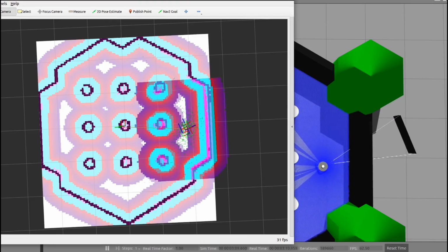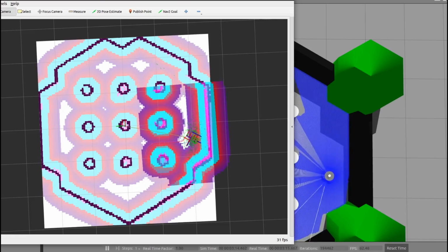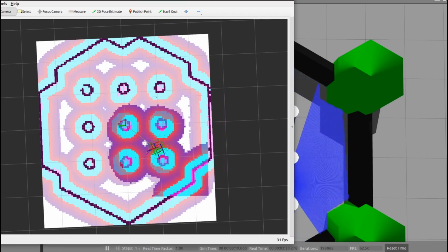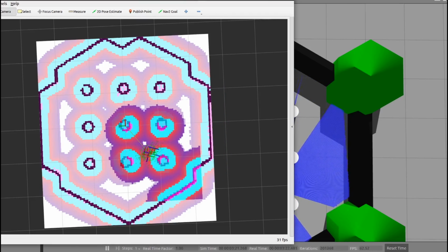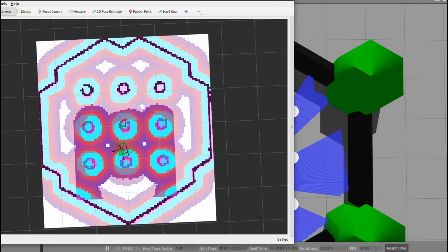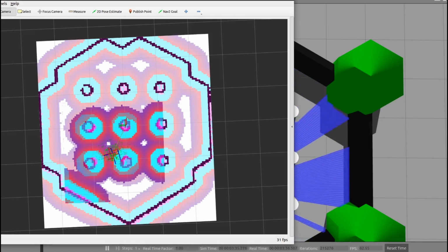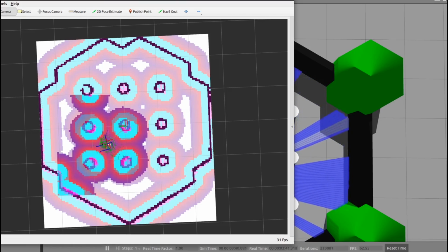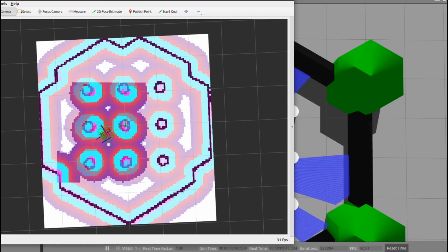As a recap, we started with creating a simulation in the world. We then added our Nav2 launch files so that Nav2 can start and all the infrastructure for Nav2 is complete. After that, in this video, we created an application layer, which is supposed to be the main place for our application to run. In a real scenario, it would have all the compute. Let's say you have a vision module. The vision module will be able to decide where the robot should go to. And then using that, you would be able to ask Nav2 to move the robot to a certain location. So this was the project about a patrolling robot in Nav2.